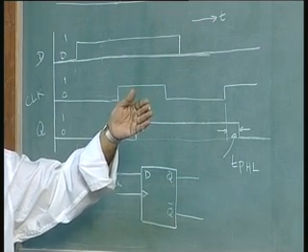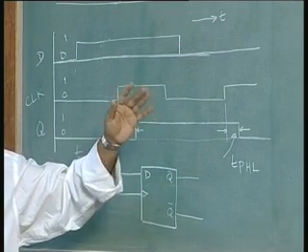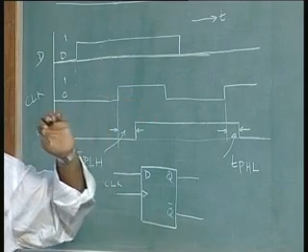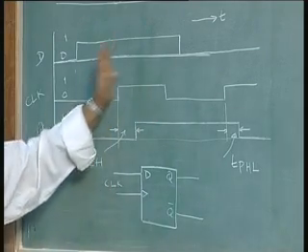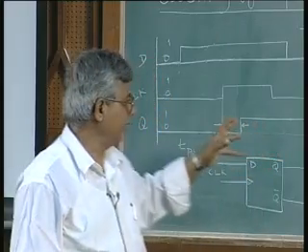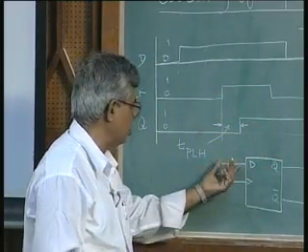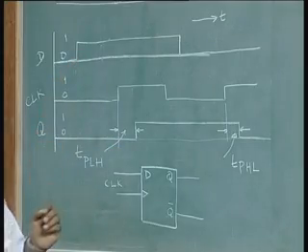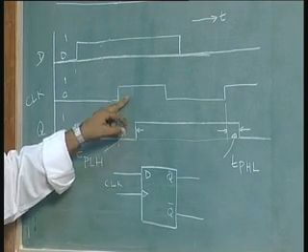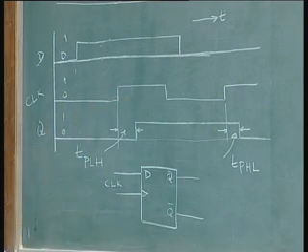So, this is of course not a technical reason, but technically we will see how this works. But what I am saying is, before any activity we should be clear about the intention of the circuit. That means the circuit intention is the input has to change from 0 to 1, and that intention should be made very clear before the clock arrives, and how early should it happen. That is called the setup time.